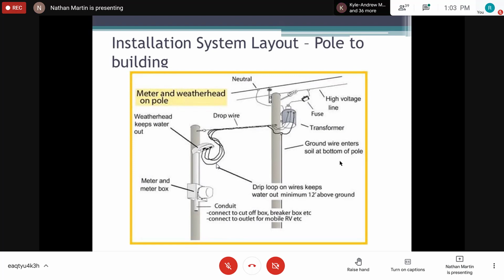So you put a layer of sand at least 6 inches, right, and cover it to ensure that if somebody is doing some excavation, they come across a bed of sand before they reach the cable, right? So it's really to protect the cables from excavation.